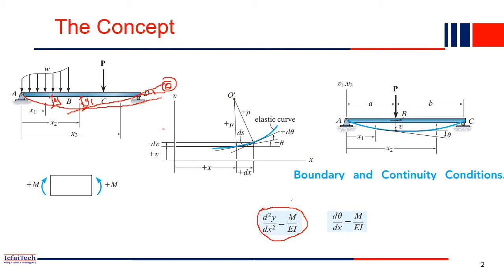Let me draw here. Consider a beam. This is a simply supported beam, so one end is hinge, another end is roller, right? And some load is applied, maybe a UDL. Because of that, you have the deflection, right? Now if you draw a tangent at any particular point, this tangent makes an angle with the horizontal, maybe theta. This theta is anti-clockwise, right? So we are bending anti-clockwise from the axis. This is a positive theta, so that's what we considered. This is very important to understand here.